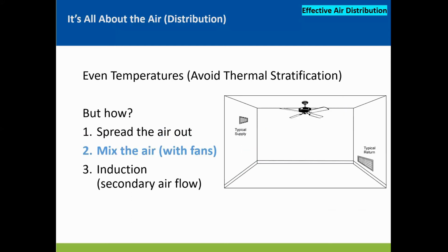You can mix the air up with a ceiling fan. That actually adds energy into the space. So maybe not always the most efficient way to do it, but it does add to the comfort of the space, and it's a good way to do it. And maybe it's something you want to do when you're not actively heating or cooling. So ceiling fans have their uses.